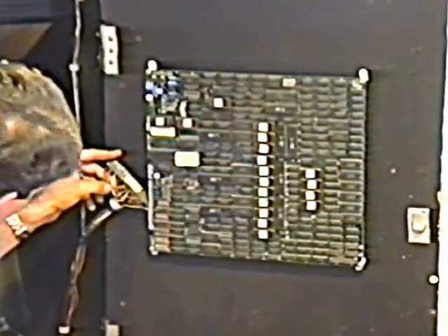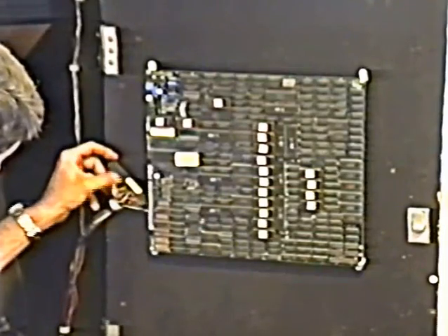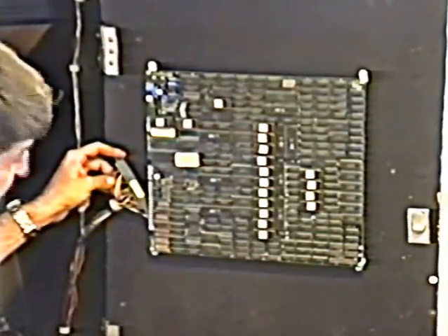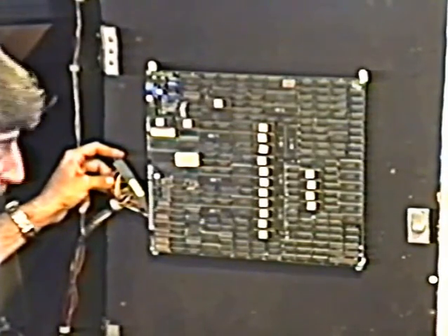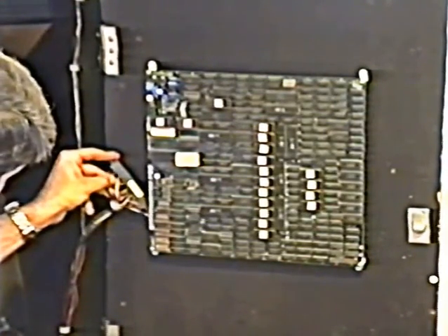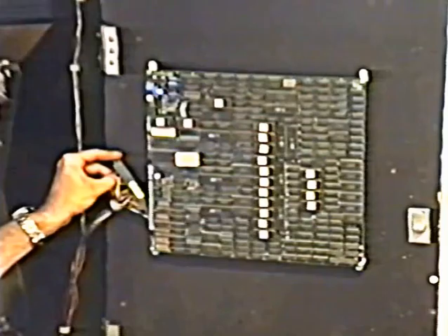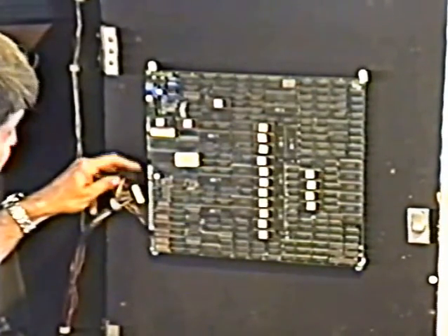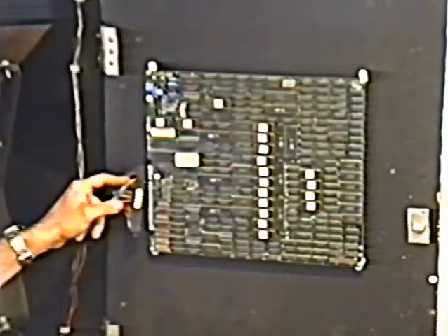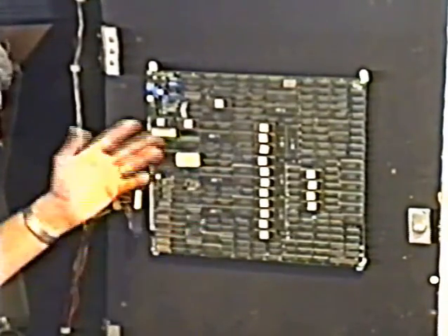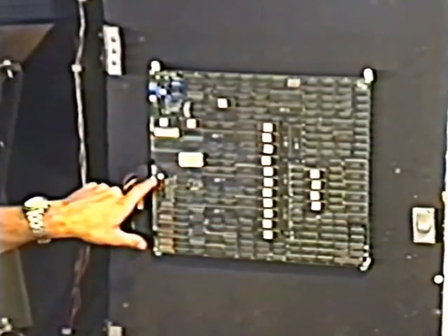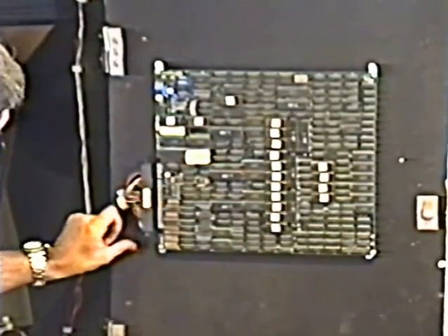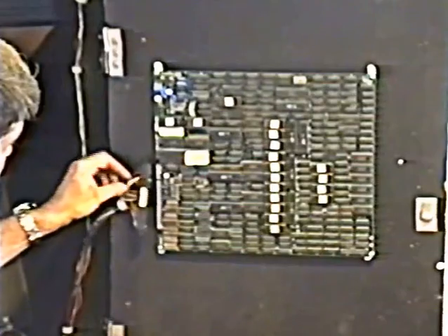It apparently is not used in this game because I have the ground wires, they're black. I have the red wires, that's for the plus 5. Then there's a blank spot right here. Pins 5 and E are not used, so this game doesn't use the minus 5. If you have a standard connector with minus 5 hooked up, and the board doesn't use it, that's okay. It's just not hooked up to anything. On the board here, there's a little pin, but it's just not used. And then the yellow wires for the plus 12.